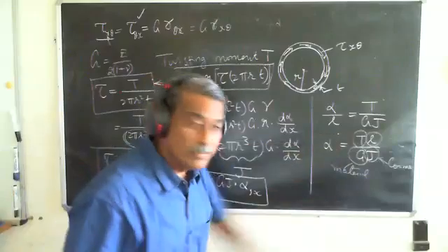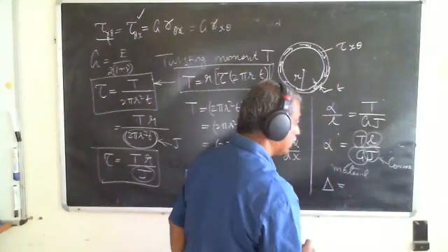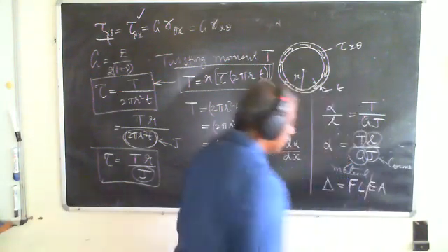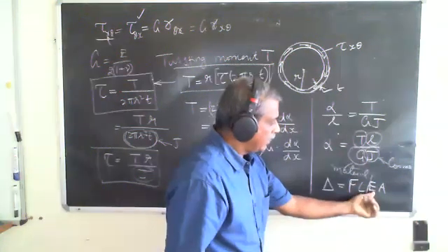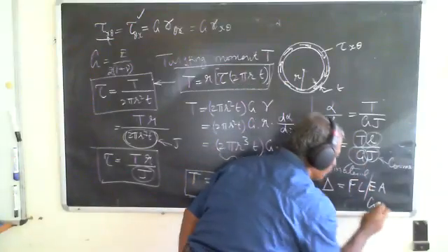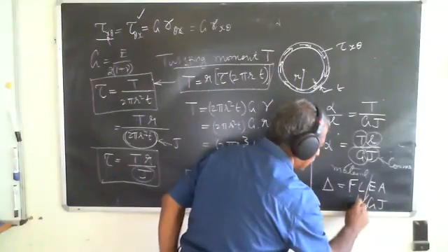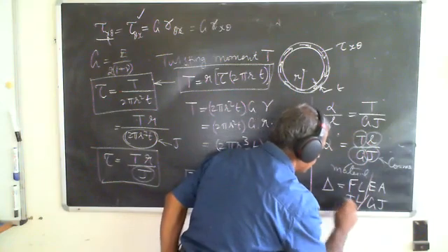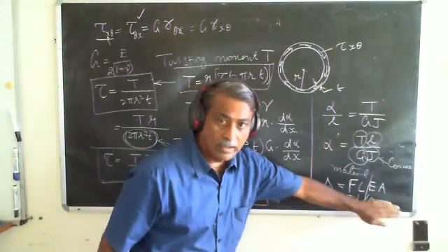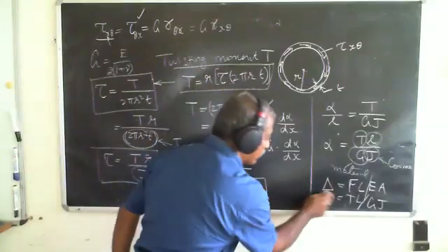But this looks very similar to what we did for axial, which is deformation, elongation equal to P L by A E. If I replace E by G, replace area by J, keep length constant and T over here, I will get alpha. So I don't have to remember this formula. I just have to replace appropriate quantities. I will get the angle of twist.